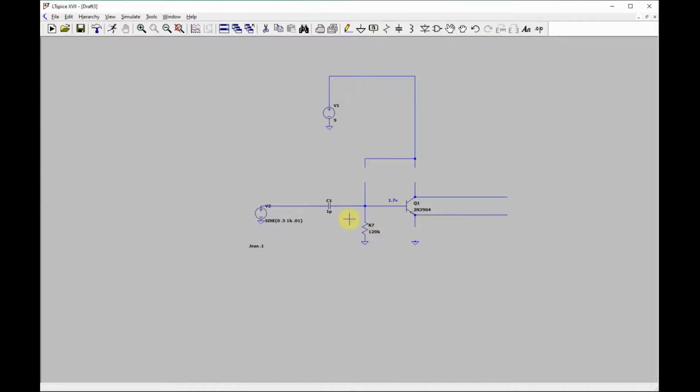Okay, so you've got this here. We already said that we need 100K input impedance, and you'll see how it works as we go, especially if you watch a few other videos. But the reason this works out this way, and I'll explain it ahead of time, is that when you're looking at the input impedance coming into this device, it splits this way, and this way to 9 volts, because AC sees the 9 volts as a ground, and then you've got a third way that splits down here.